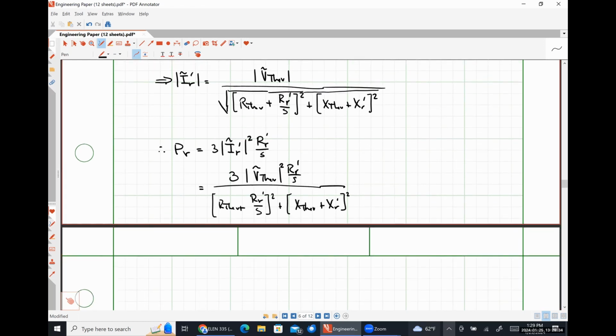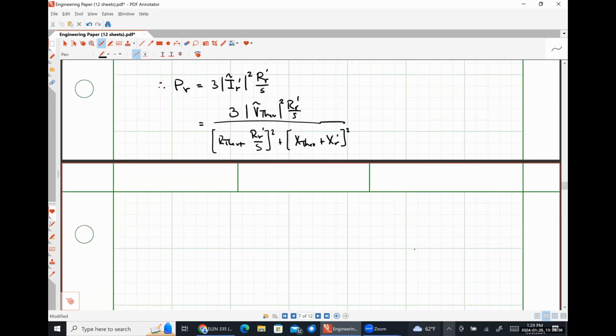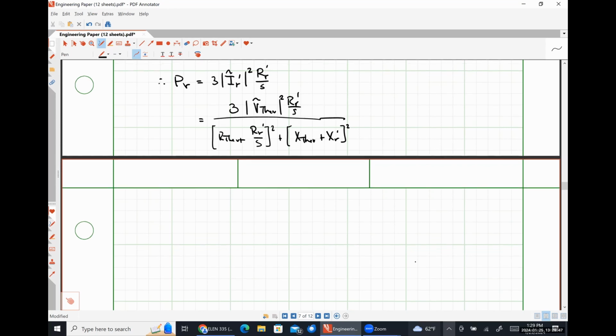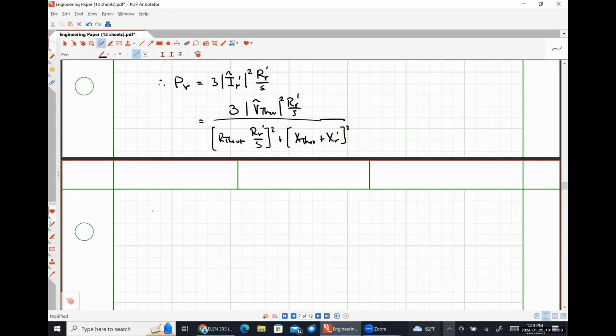So let's take a moment to figure out what our torques are going to look like as well. Our mechanical torque is just our total rotor power divided by omega S. So that's literally just going to be our exact expression that we just wrote down, except that there's another omega S distributed among the denominator, right?